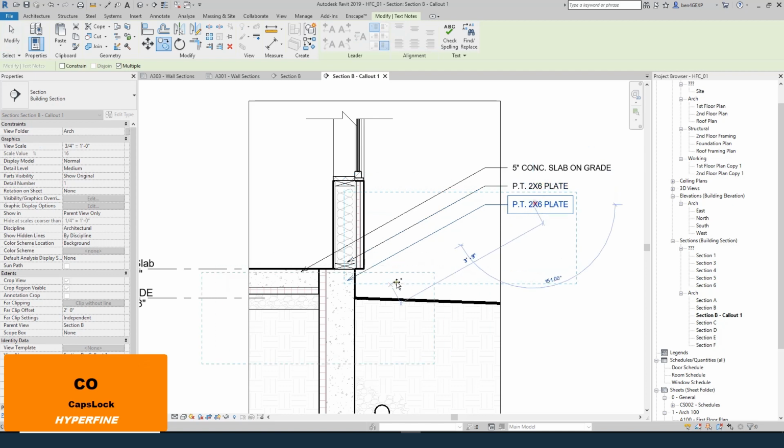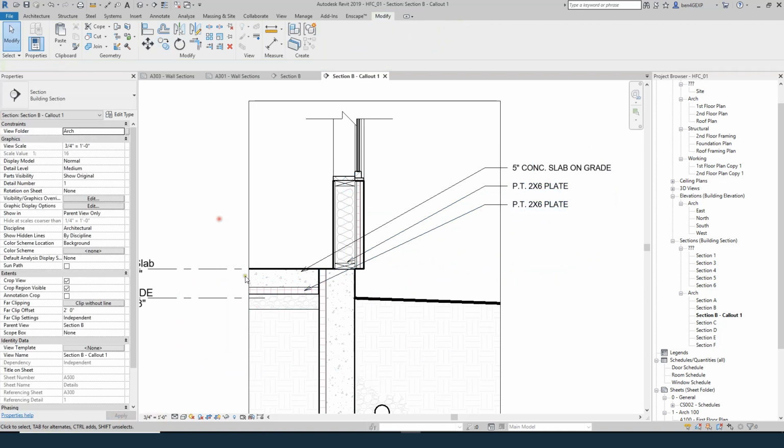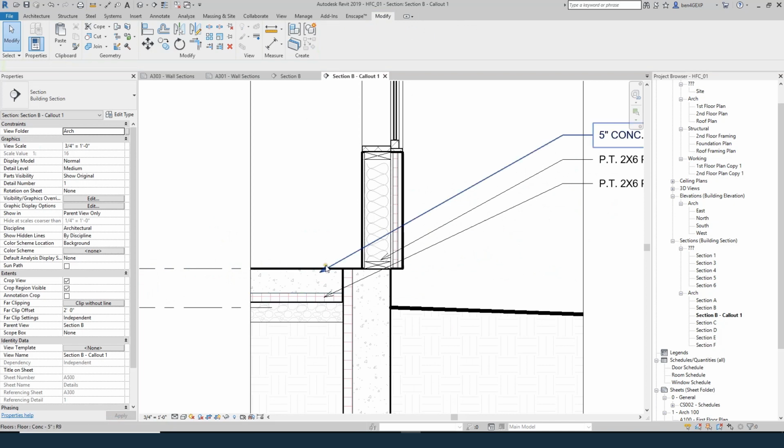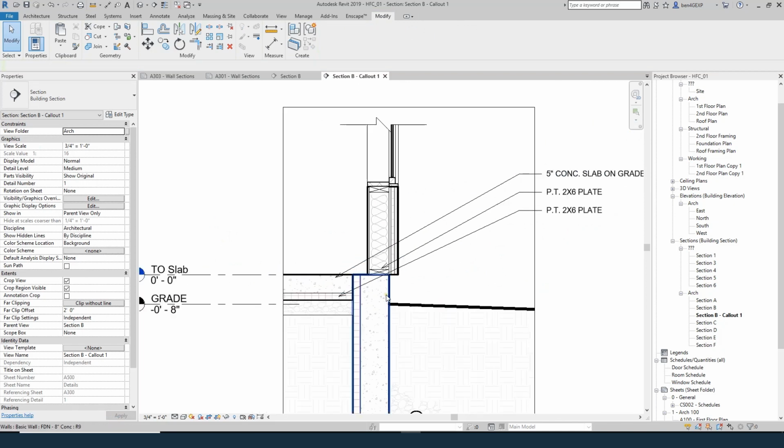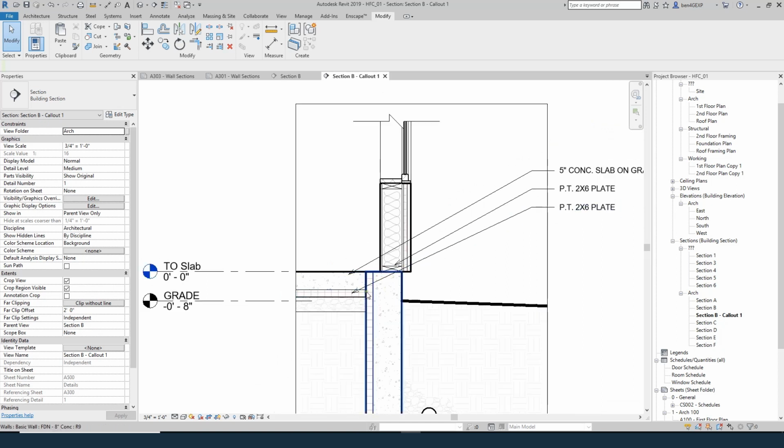And you just continue pointing down the different layers. So this is a very generic, there's lots of different ways to do a slab on grade. Sometimes the slab will be continuously poured with the concrete foundation wall. Sometimes it'll go over top. Lots of different ways to do it. This is a very generic method where you pour the concrete foundation wall, you put your insulation in, and then basically the slab on grade gets poured inside of the foundation wall.